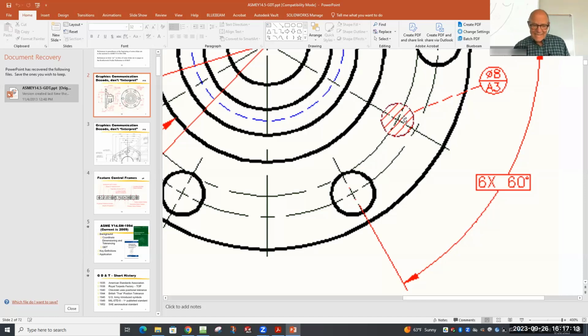The reason for that is this. If for some reason I don't have a surface plate that I can set that on, I have to have that sitting on 3 points of contact. So we go back to Grayson, my tool maker. He makes me another gauge like that that has those 3 little pins. You see those pins on there? Can you see them okay or not?